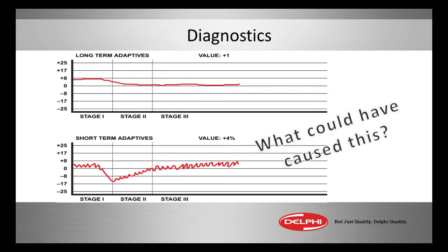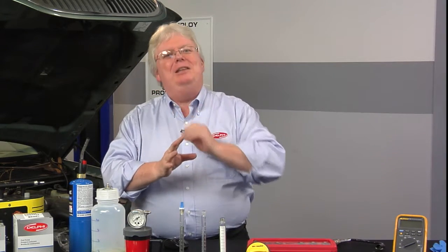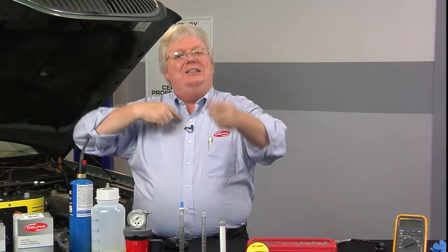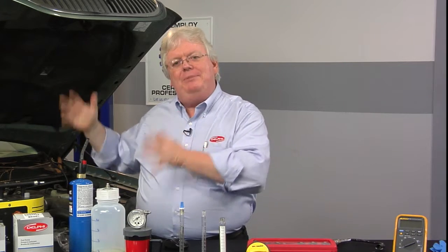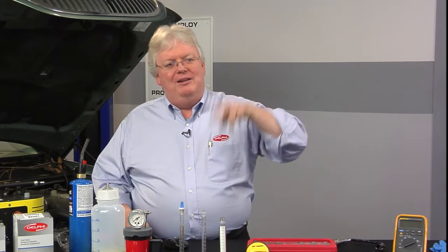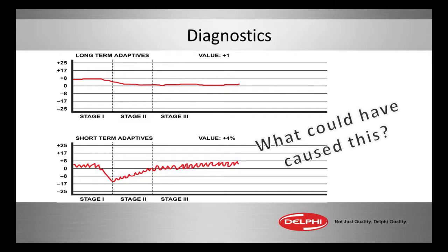So as O2 starts going down, being leaner, you would see shortly after that, almost immediately, but not exactly immediately, the trim go up, and as the O2 value goes back up, as it shifts back and forth to keep the catalytic converter happy with oxygen storage, and also make sure the computer knows that the O2 is working because it's switching back and forth. We will deliberately do that with fuel injector pulse width, slightly varying each side of stoich. We'll also see the trim move back and forth too. So that wiggly trim you see in the bottom picture, that's normal.